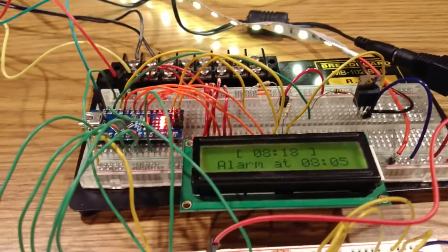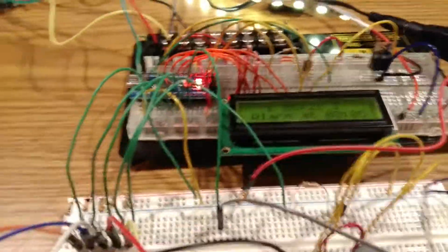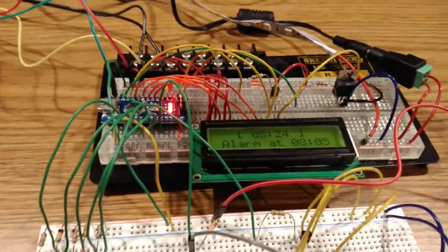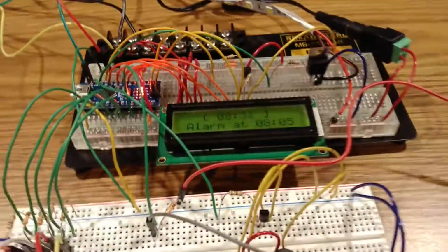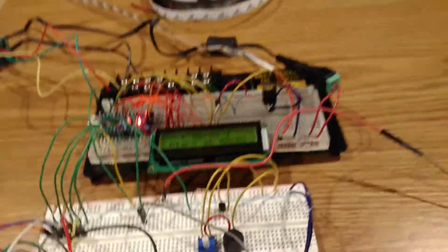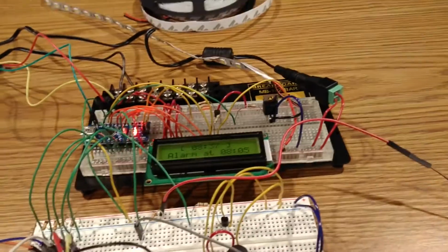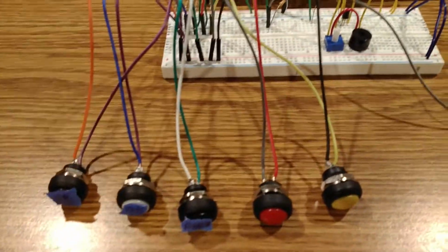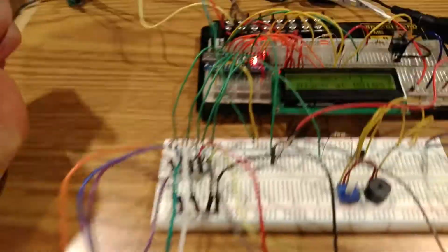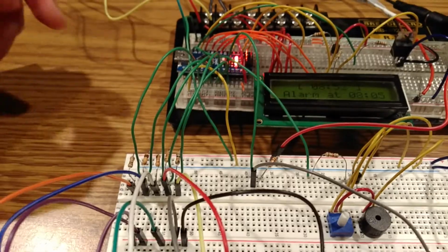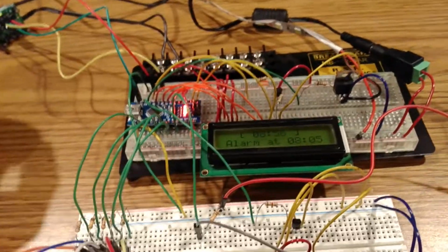So I went ahead and disabled that. I'm going to take this off here. So that in a nutshell is all the features that I added. I can go over the hardware briefly here. The buttons are all momentary switches, so just single push switches. So I had to debounce those as well as use resistors to pull them down.